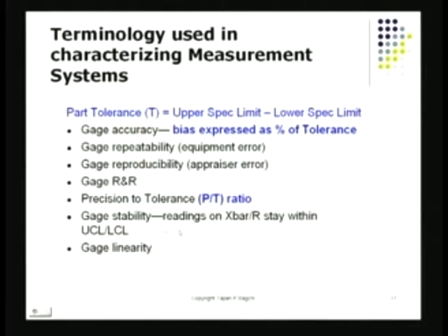Then of course, if I'm using a system that can shift its performance over time, I may produce some control charts, and that is to be done with some standard objects. I may take some standard objects and measure their dimensions at various points in time, and produce a control chart with this. The control chart can tell me if the measurement system itself is drifting or if it is staying stable. That's something I can do quite often by plotting various types of control charts. That's a pretty decent approach, in fact, to make sure that the system stays the same as time goes by.